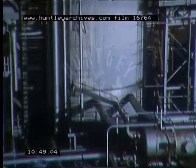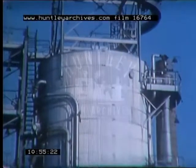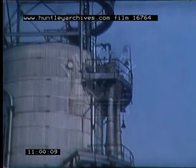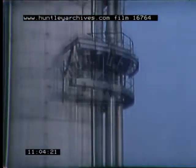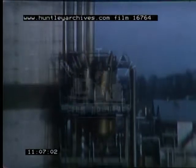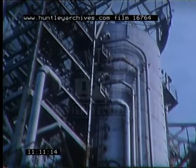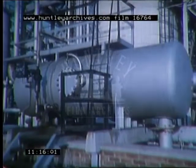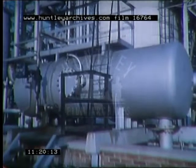Remember that inside the tower there are 25 trays and a packed section. The vacuum in the tower is maintained by the ejectors which draw off steam and uncondensed vapor from the top. The first stage ejectors are at the top. Their condensers, together with the second and third stage ejectors and condensers, are lower down. The vacuum gas oil is drawn from below the packed section near the top of the tower. It is collected in a reflux receiver, cooled, part returned to the tower as reflux, and the remainder sent to storage.